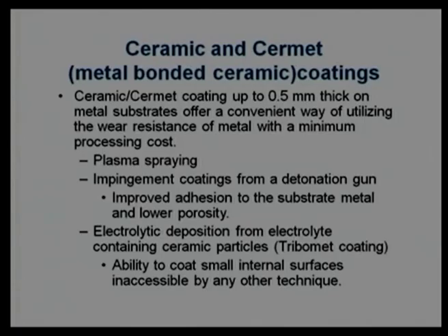Reduction in friction occurs because of the low chemical reactivity or low adhesion, but abrasion will be rare as they have a very high hardness. That is why they are known as wear resistant coating compared to friction reduction coatings.